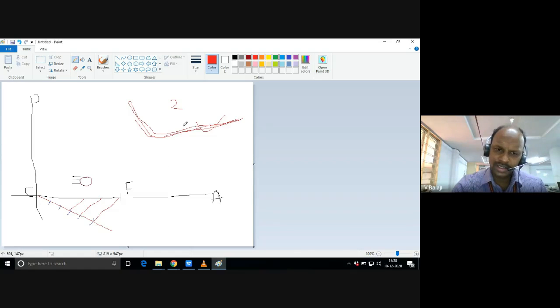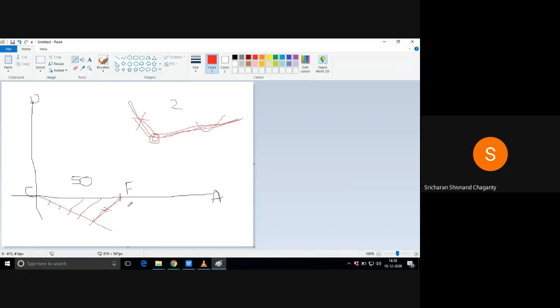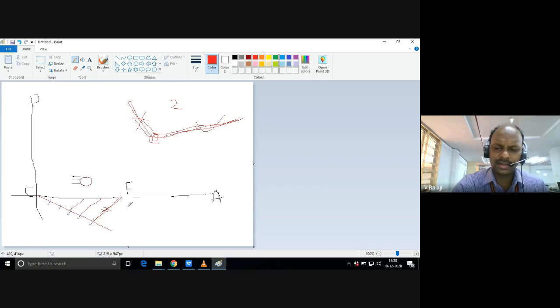You need not worry about the other short edge of the mini drafter. The longer edge you just match to this particular line. Just move the drafter after tightening the mini drafter knob, parallel to this particular line. Am I clear? Yes, sir.